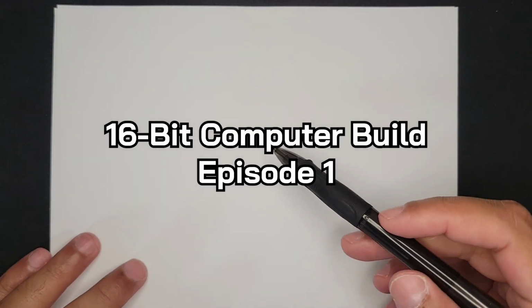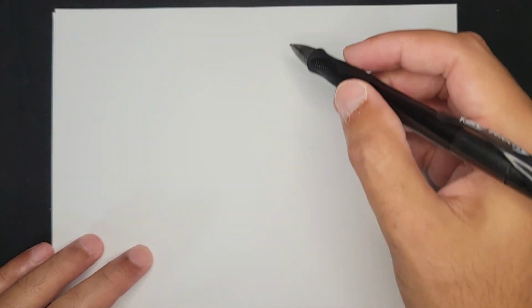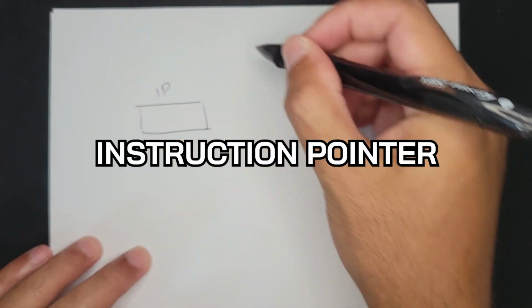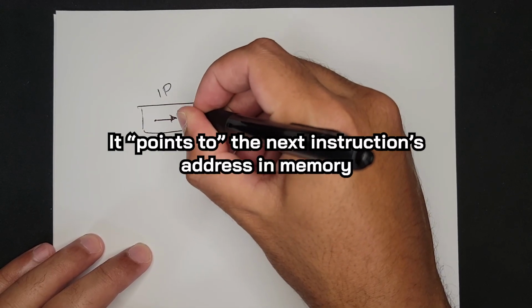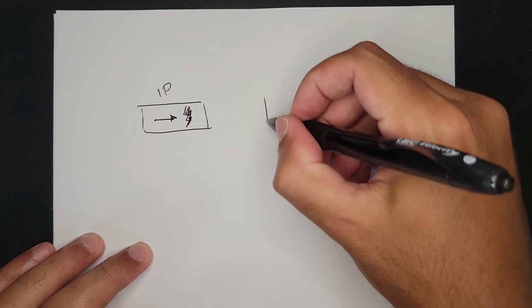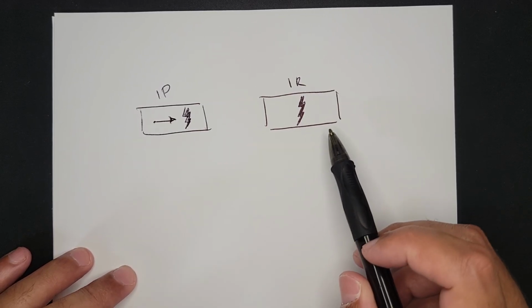So let's talk about the 16-bit computer that I want to build. What I want to start with is the fetch, decode, execute cycle, which is sort of the core operations of the CPU. We have instructions, right? And we have two registers for instruction processing. We have the instruction pointer, and this is going to contain the next operation to be executed. So I'll put like a little lightning bolt there with an arrow. This is the next one to be executed. And then we have the instruction register, which has the actual instruction that is currently being decoded.